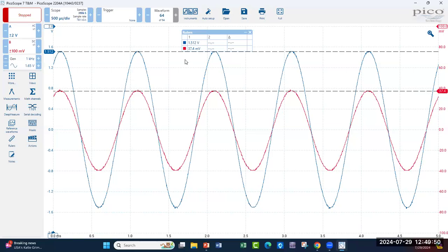Well, nothing wrong with our display, nothing wrong with our hookup. What is wrong is the probe itself. Your oscilloscope probe has a slider. We talked about this quite some time ago when we looked at leads on our machines, and the oscilloscope probe has a slider switch. You slide it in one direction and you get what's known as a one-time reading. You slide the switch into another direction, you get a 10 times. So right now, as I'm looking at the oscilloscope probe on the board, it is on a 10 times.